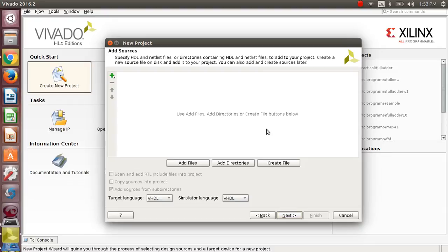In the simulation source file there will be the test code of your circuit, that is, what values you are giving as inputs to your circuit, you have to initialize in your simulation source file, which is also called the test bench file. So remember about that. In the next video I'll tell you about the simulation source again.